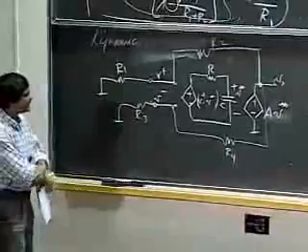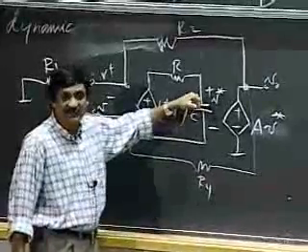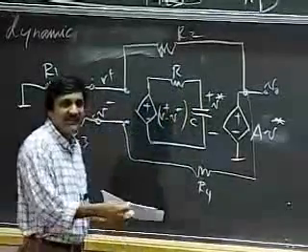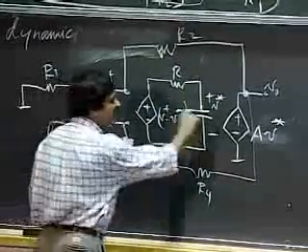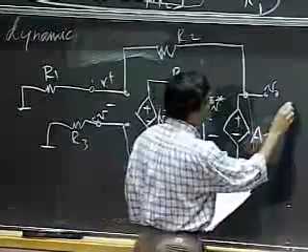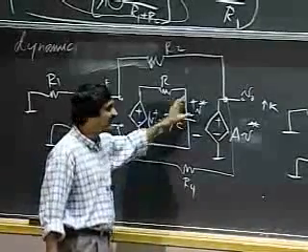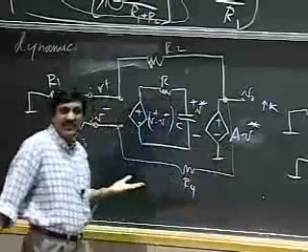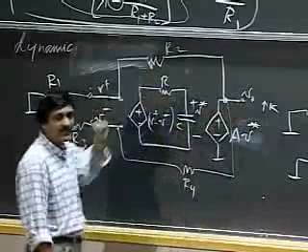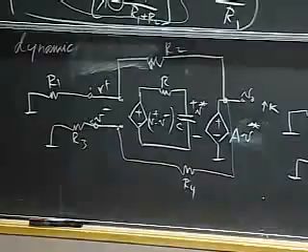Okay, just to give you some insight into what we're going to see, notice that if I make a small perturbation in the voltage across the capacitor, let's say by applying some initial condition kind of thing onto the capacitor, then let's say the output changes to some value K. So the change on the capacitor must have been K divided by A. And what we're going to see is what happens to the op-amp when the initial condition on the capacitor is such that this output gets perturbed to the value K. Okay, so let's write an equation for this little circuit and see what happens.